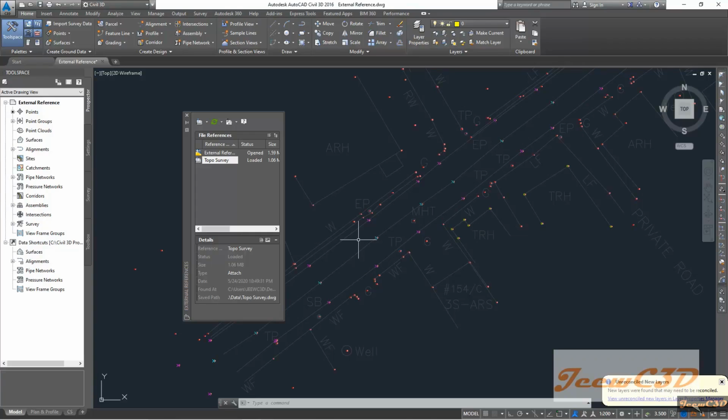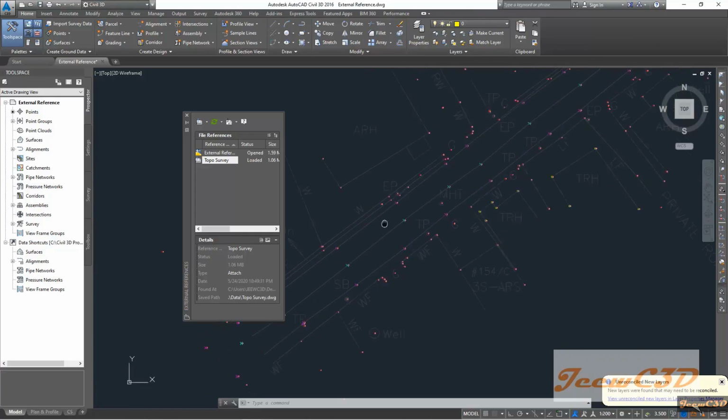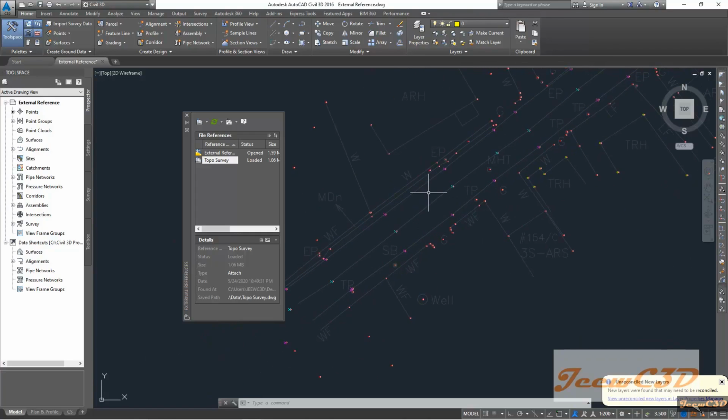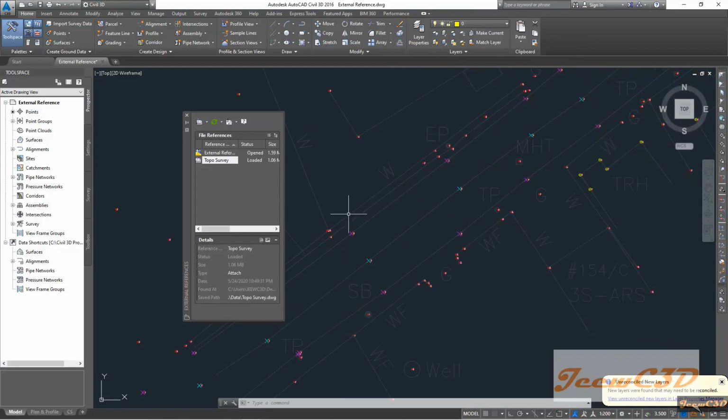But if they are at the correct locations, but we have done it in the wrong way, we can find out that we have done something wrong by externally referencing a drawing. If we have done something wrong, this external reference drawing will not coincide with this drawing.